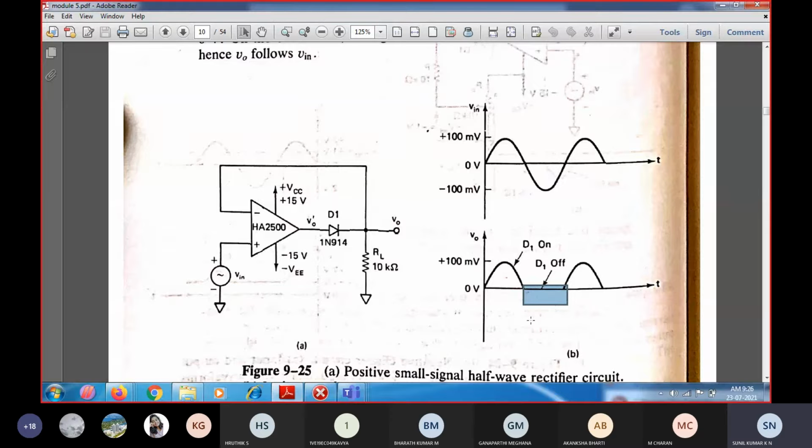Since the circuit output remains 0 and the feedback path is affected, the op amp will get saturated in the negative direction, at minus Vsat. So the output settles at 0. During the positive cycle, you will get the same output as the input, because diode D1 completes the feedback path. The circuit functions as a voltage follower, so the output is the same as the input.